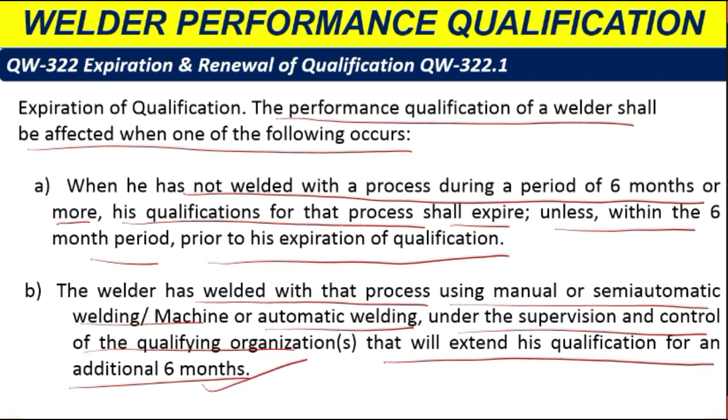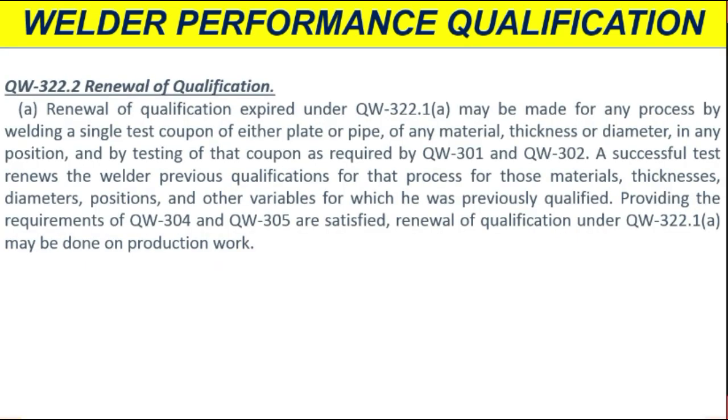So this is the 6 month duration gap, and if it is longer, then requalification is required. For the 6 month gap, we can do another additional extended qualification if the welder is working as per the requirement. And the very last one is QW 322.2, renewal of qualification.